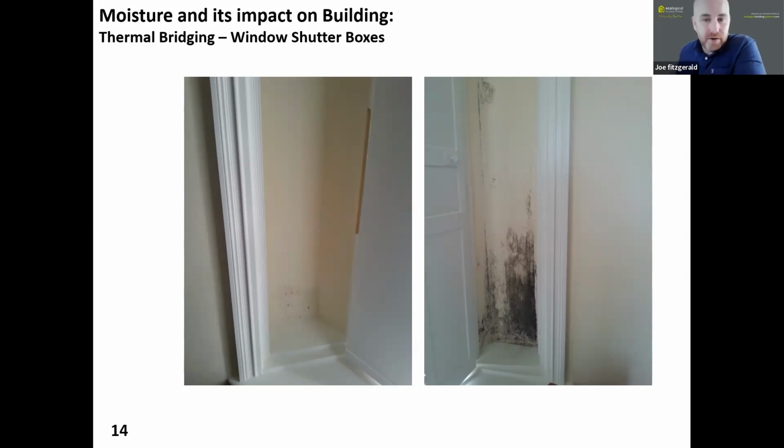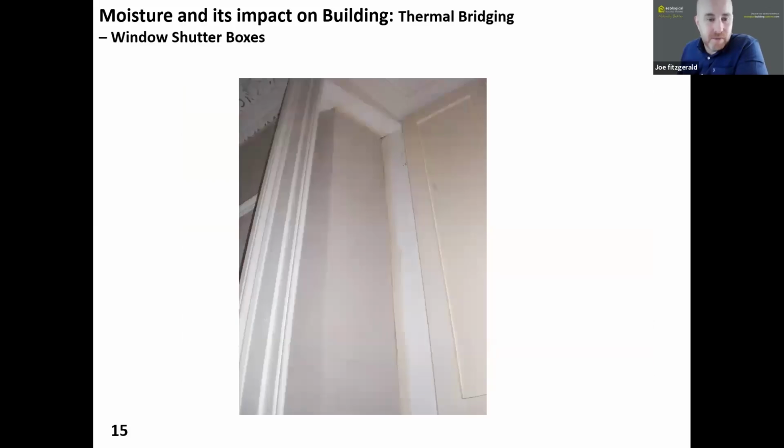So we went out, had a look, realized it wasn't insulated. We told them, clean it down, you know, kill the bacteria, insulate it with a small piece of calcitherm. We came back a couple of weeks later, everything was fine, and it's been fine since. So just taking away one of those conditions, it still had poor ventilation in there, but it didn't have the cold surfaces anymore. So even taking away one of those things has improved the capacity of that building to fight things like mold growth and condensation.